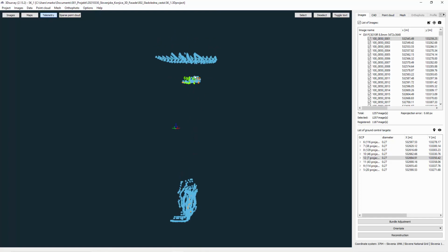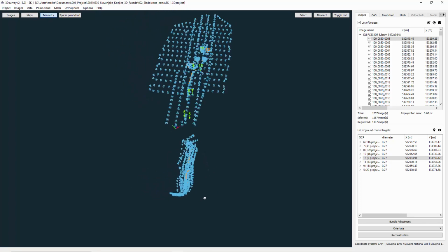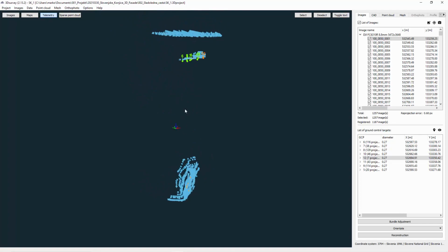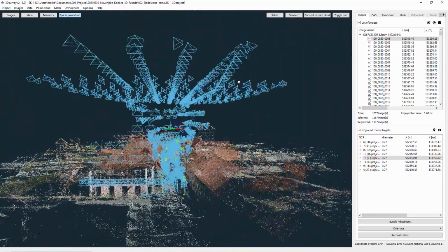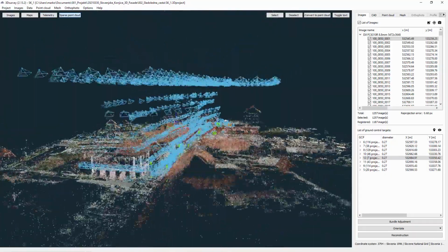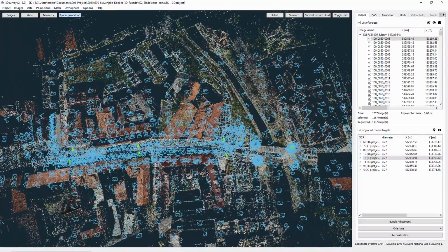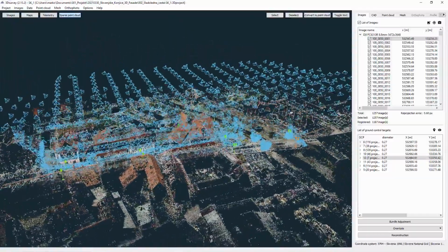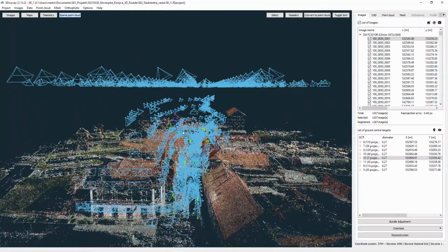The thing was, here we have an RTK signal and accurate position, then we turn off the drone and start with manual flight. We didn't get an RTK position and the height was not calculated referentially correctly, but nevertheless we get the end results like you can see here after the bundle adjustment. So all cameras are correctly positioned after the bundle adjustment. You can see we also used 1, 2, 3, 4, 5, I think 8 ground control point targets, and those blue pyramids nicely show us the position of cameras.